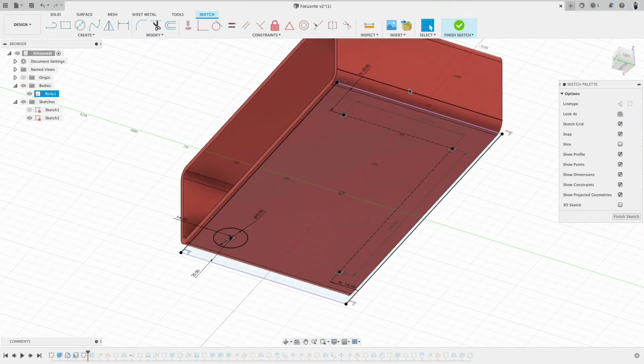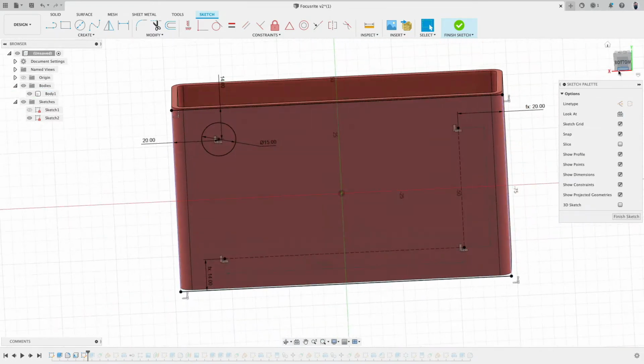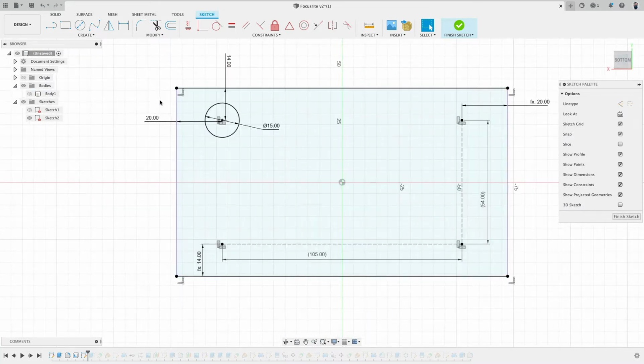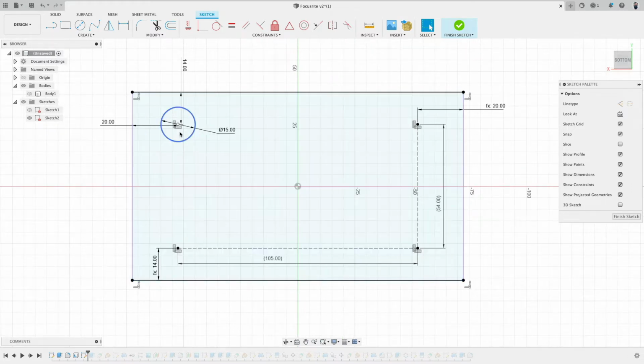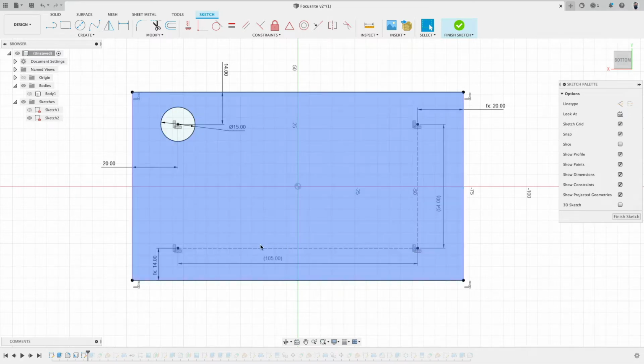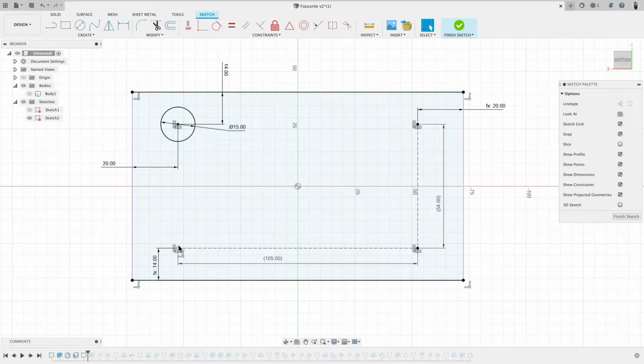This edge and this edge, because this is the left and right side, and I have the height, and then I drew in the missing two lines. Here's a ring, diameter 15 millimeters. From the center to here, it's 20 millimeters, and from the center of the ring to this edge, it's 14 millimeters. Now later we have to make actually 4 pieces, so 3 copies.